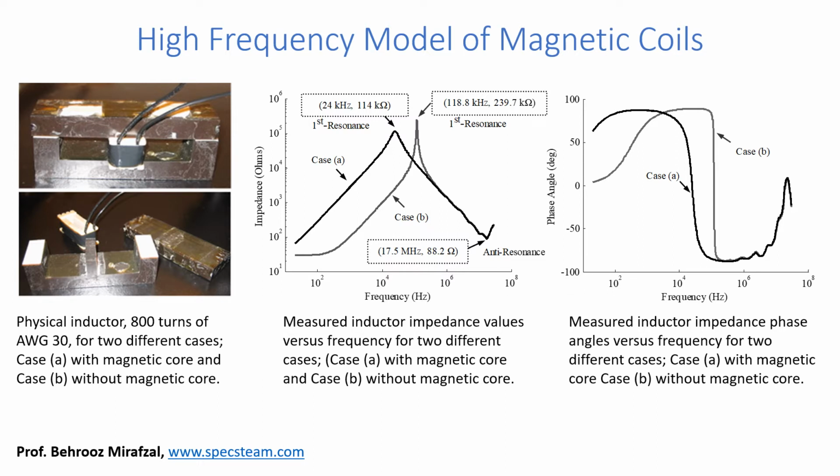So when we reach very high frequencies in the range of megahertz, you remember the reflected waves were in the range of 1 megahertz. So if you go above 120 kilohertz, no matter which type of core you have, both demonstrate the same behavior, and that's the reason the stray capacitance is going to be dominant there, and no flux is going to penetrate the core at that frequency.